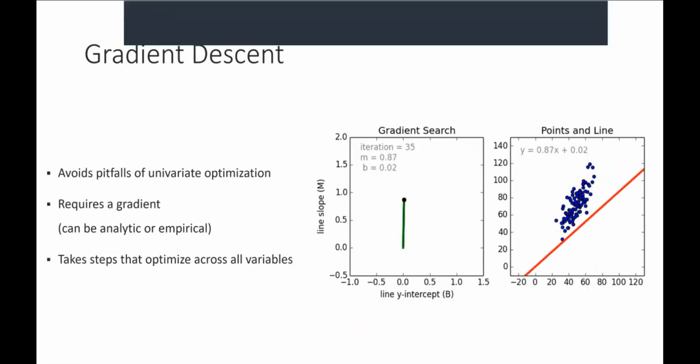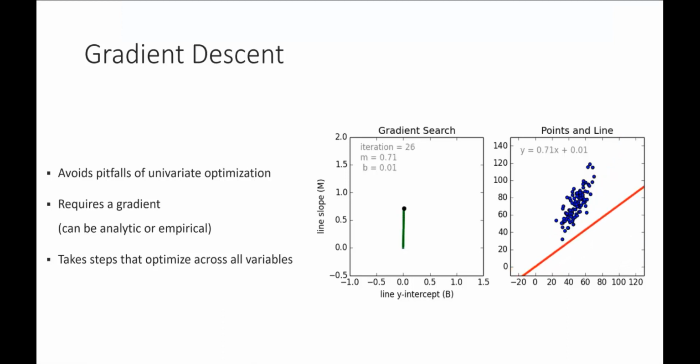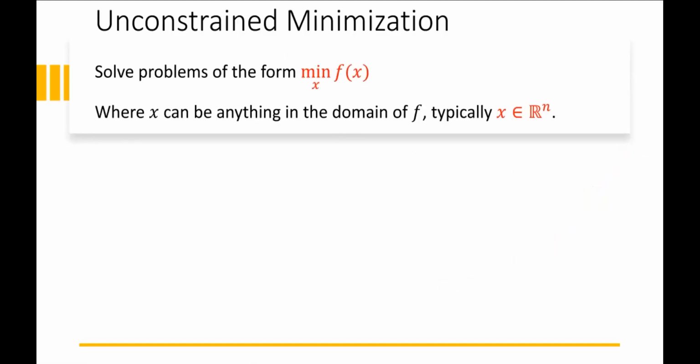So that brings us to our new material, right? We've talked about a couple of different solutions for this optimization problem, but now we're going to get into a bit more detail of why this works. So finding the position for IK, right? We're given some end effector pose that we want, and now we want to find the joint angles that will get us there. This can be framed as a minimization problem. This is just part of an umbrella of optimization methods, but today we're going to talk about unconstrained minimization. And unconstrained minimization is any problem of this form.